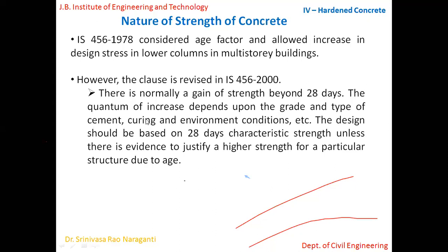Then curing depends on what kind of curing you're doing. We'll be discussing in detail about the curing methods, but whether curing is water curing, or using pressure, or using membrane, or curing type. Then environmental conditions. What kind of environment? We have mild environment, marine environment, all those environments. So what it is saying is concrete gains strength after 28 days. There's no doubt about it. But how much it gains depends upon all these factors.